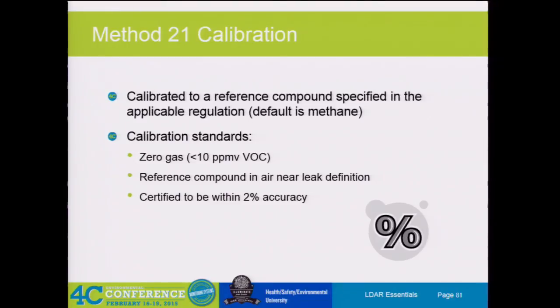But if you don't have that, and let's say you just go zero and 10,000, you only have one point out here, so you have this huge gap. If you're at a 100 ppm leak definition, it's not going to come across. It's now so far off base that it wouldn't be accurate. So you have to calibrate to the closest leak definition of each type that you're doing to make sure that it comes across correctly. Does that make sense, or is that okay?